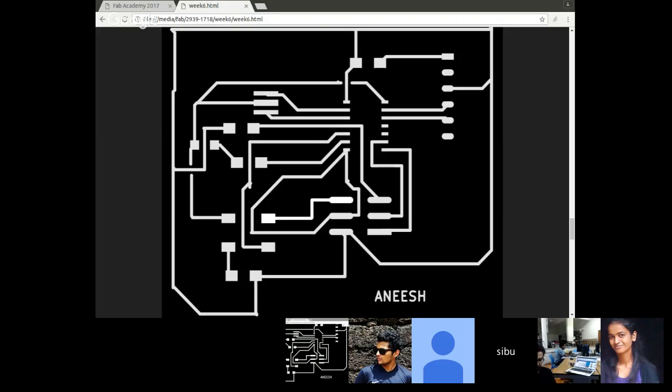One more thing you can do, while using these sharp corners, right-angled traces, is filter them like this, as you did in this track. Also, Anish, this is not the way to add a 0-ohm resistor or a jumper. You are ending the tracks just like that. You have to have a pad. I had to connect it somehow to get the board working, but this is not the way. Sibu helped me solve it, so I'll be soldering it again tomorrow. And Neil doesn't like jumper wires, actual wires.